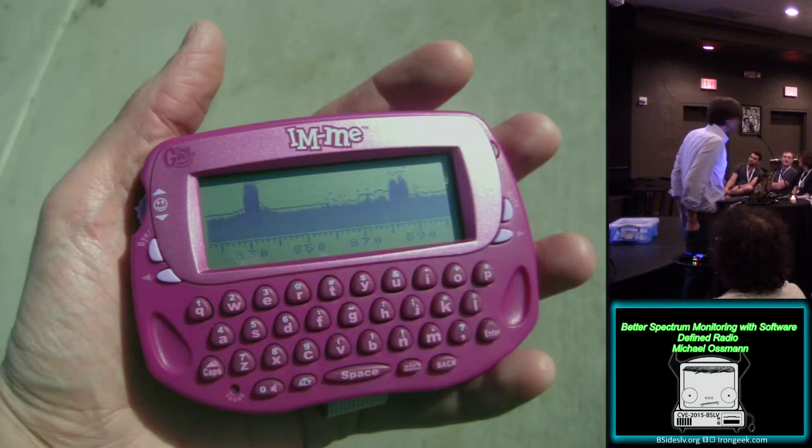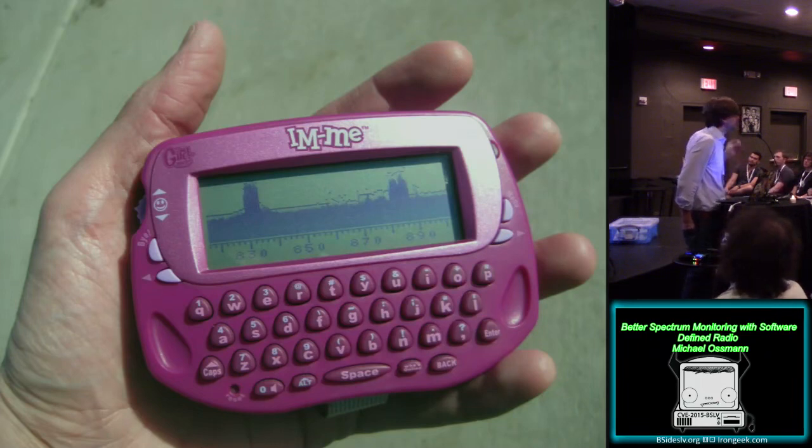The IM, I was introduced to by Travis Goodspeed, and he taught me how to program it, and then I said, hey, I could build a spectrum analyzer out of this. So I wrote software to be a spectrum analyzer, and what it does is it tunes its little radio chip to one frequency, takes a measurement of the radio energy, and then plots one pixel to the screen, or one column of pixels to the screen. Then it shifts over to the next frequency, and it tunes the radio, it takes a measurement of the energy, and plots a column to the screen, and so forth. And it sweeps across this 130 pixel display many times per second, 20 some times per second, something like that.